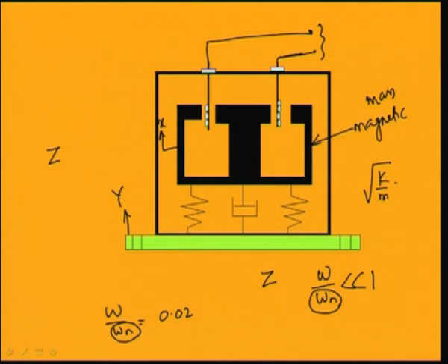So, you should have a system with very high stiffness and low mass, that is, a low mass with a very stiff spring. When it is vibrating, the magnetic flux will create current in these coils, and from that coil you can measure the relative displacement and find the acceleration of the system.